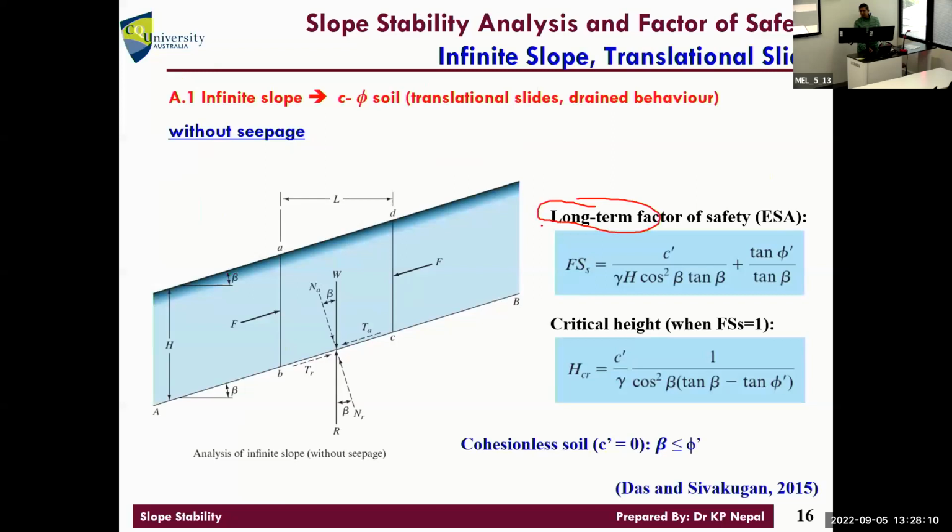Long-term means, after you see this drained analysis we talked about during our modeling also, yeah? Drained analysis, after a very long time, water goes out, right? Squeeze out. So it's a drained analysis for the long term, but short-term is what? We just apply the load immediately because water does not get a chance to go out. Good, yeah? The total stress analysis we need to do.